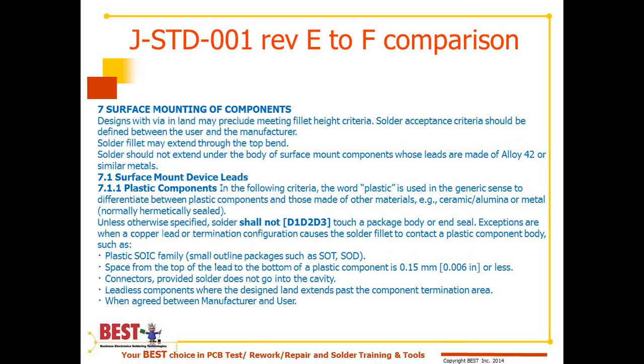It says, unless otherwise specified, the solder shall not touch a package body or end seal. Exceptions are when a copper lead or termination configuration causes the solder fillet to contact the plastic component body, such as in the plastic SOIC family or SOTs and SODs. The space from the top of the lead to the bottom of the plastic component is 0.5 millimeters or less, so they're changing the spacing requirements.